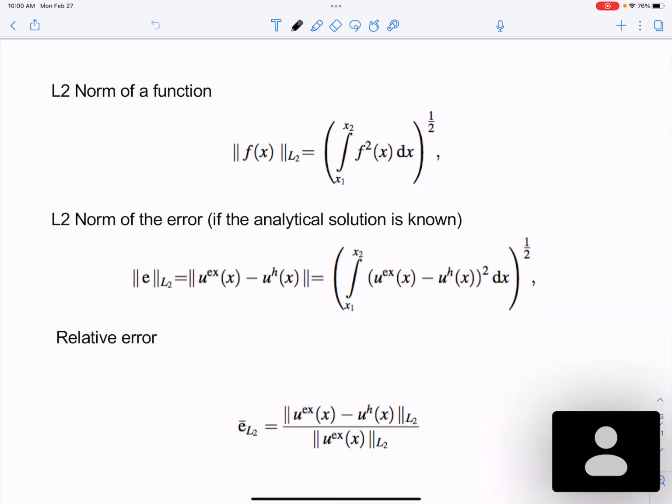This formally should be known as convergence, which means that as you reduce the element size and your weight functions become narrower and narrower, you should be getting closer and closer to the strong form. That's the idea of convergence.